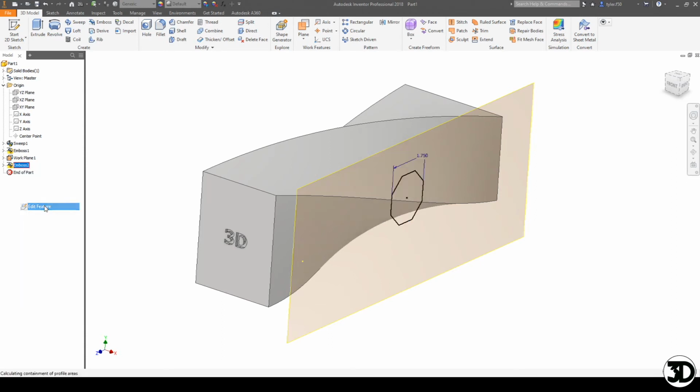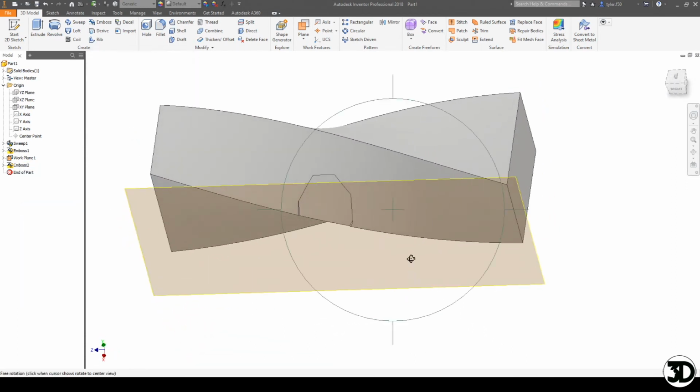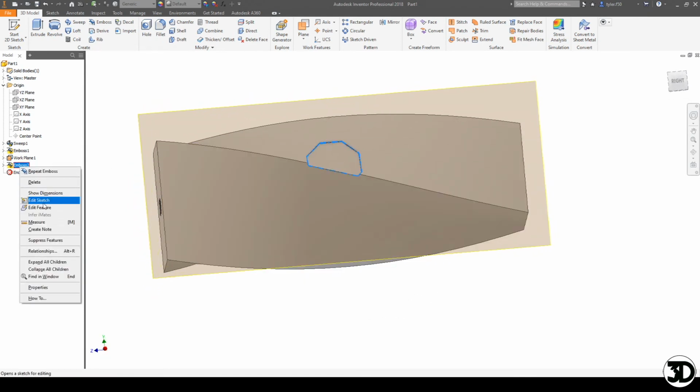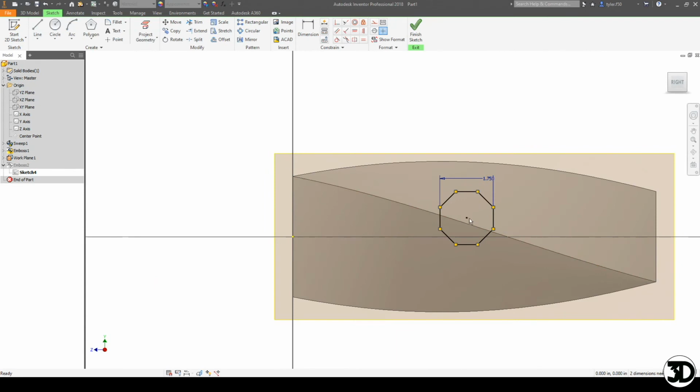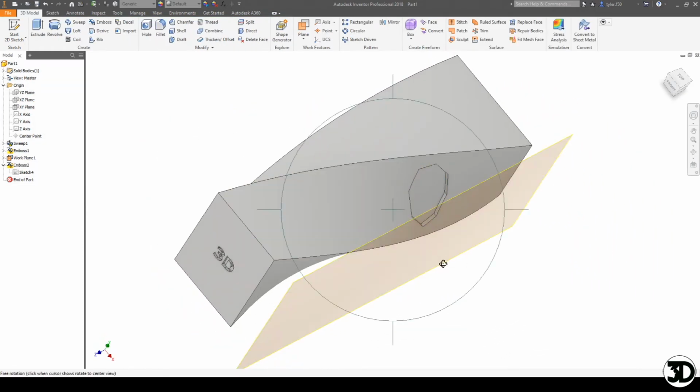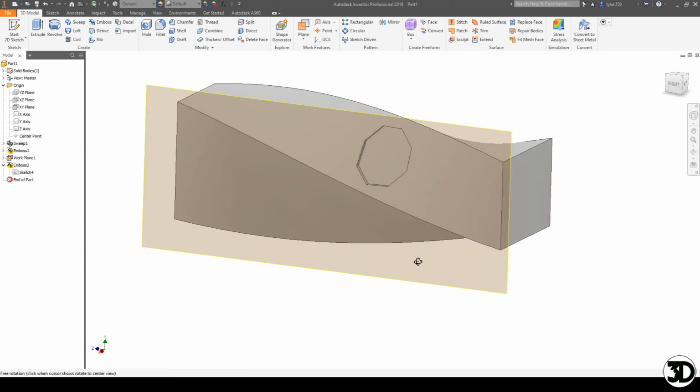Another thing you can do is edit the feature, and we can do Emboss Engrave from these spots, and it'll only recognize one surface and only go the depth that you state. So if I edit the sketch and move this, you can see that it can make a nice feature in there for you. So it's just another way of using the Emboss feature.